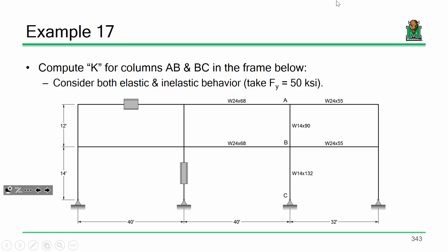Now, let me also be clear. I'm not saying that it's going to up your capacity like 250%. That's not happening. I'm saying you're going to be able to squeak out an extra 10 or 15 kips on some of these columns. We're talking about 958 kips or so, so squeaking out a couple more kips, no big deal. Does that make sense? Is everybody else okay with that? Again, we get an added perk from using tau, but really it's bringing our math a little closer to reality. Sound good?